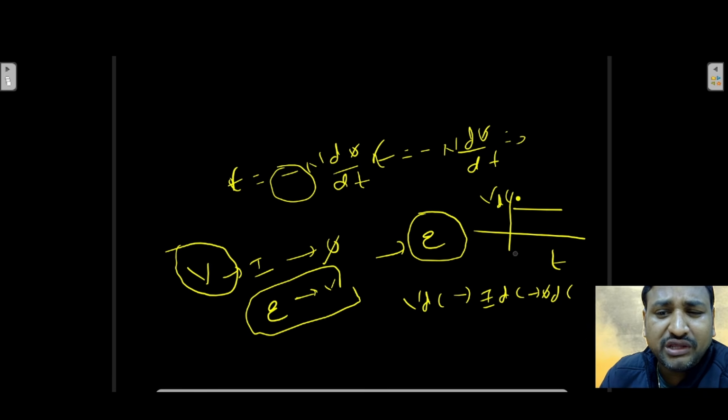If there is no induced EMF and we go on giving continuous DC voltage, first it goes into saturation, deep saturation, and if we go on giving the supply as VDC, finally it gets burnt. So what we learned is that transformers work on AC only.